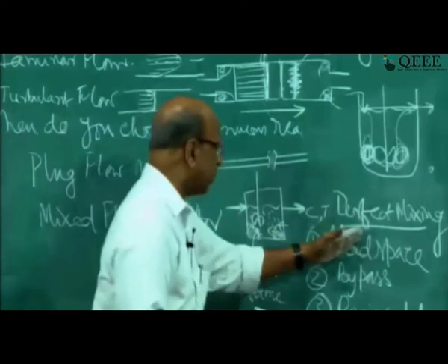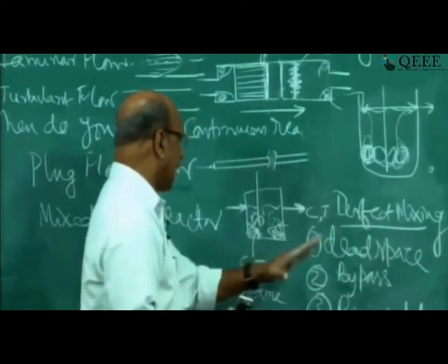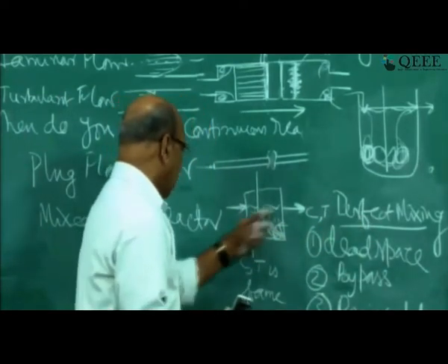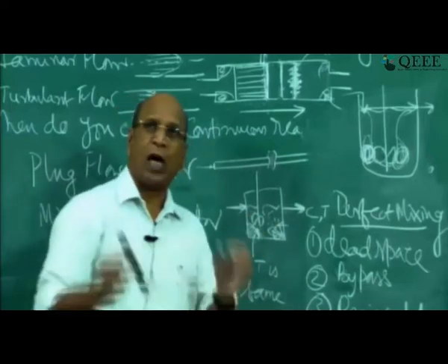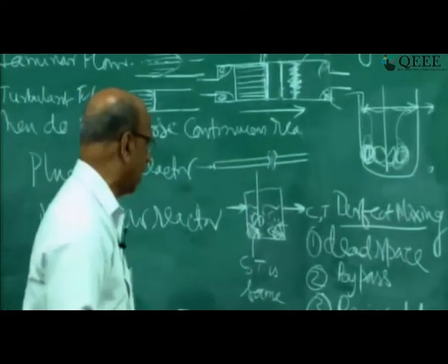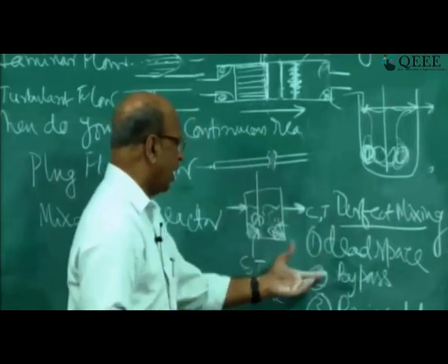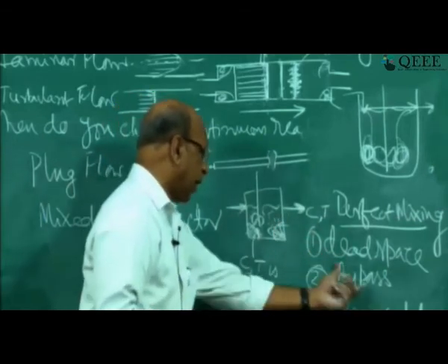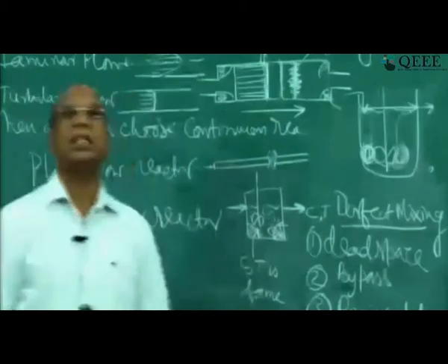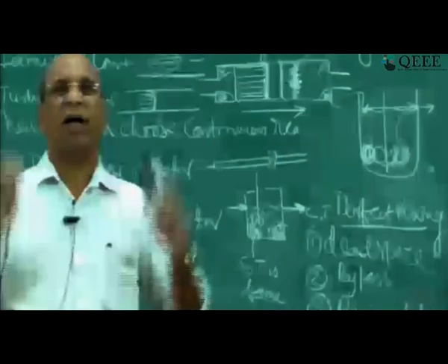And in perfect mixing, the ideal definition of perfect mixing is that each and every place in the reactor should have uniform concentration and uniform temperature. But the non-idealities are there: you may have dead space, bypass, recirculation, etc. So this is the concept of ideality.